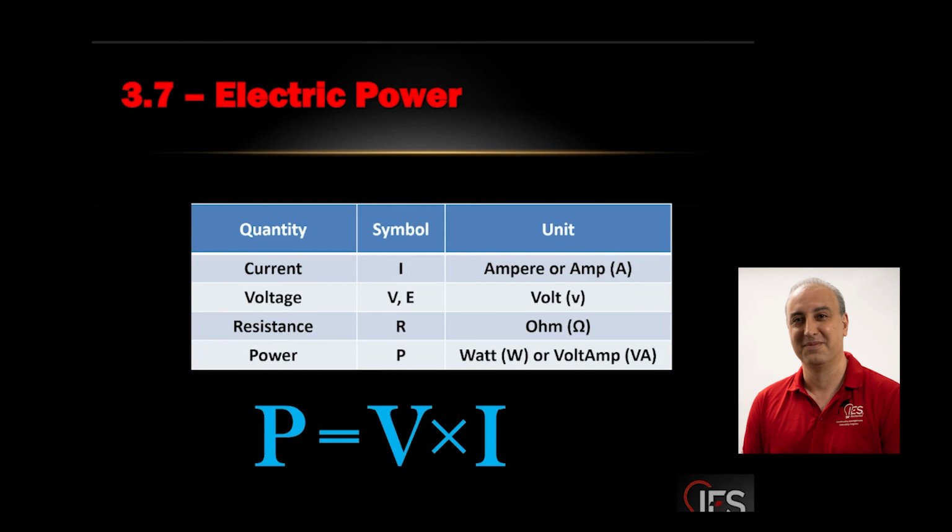And as far as your wireman test is concerned, volt amps and wattage are the same. So you don't have to distinguish them at this point. But I'll tell you why we have two, because they're not really the same. And you can understand it because you understand the theory behind it now. We said that our power source in AC keeps flipping, right? So if the voltage and current flipped at exactly the same time in an ideal situation, volt amps and watts would be the same. The problem is it's not an ideal world, right? So when we flip the voltage, current takes a little time to flip.